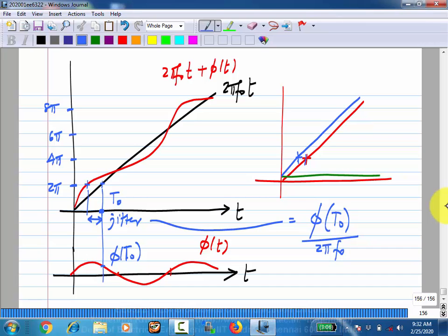What I am trying to say is that once you have this phase deviation, what you have is not a periodic signal in time at all, okay? In fact, the values of phi that are of interest are non-uniformly sampled. But if you uniformly sample it at the ideal zero crossing instants and divide by the slope, you will get the deviation. This is a very commonly done thing. This may be a point of confusion, that's why I am mentioning this. Okay.